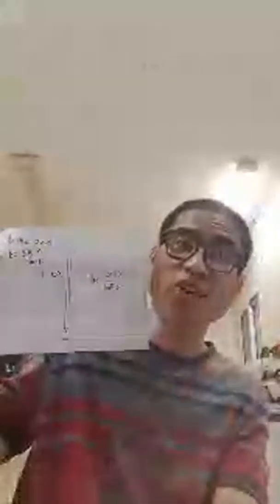Okay, so h is equal to 60 watts per meter squared Kelvin. So what is the denominator, guys? In the convective heat transfer coefficient and convection heat transfer, there's area at the bottom. But for the thermal conductivity, in heat transfer through conduction, only length matters. More on the difference, and bingo, that would be their respective units each. Okay, so you will remember that and put that in your brain cells. Get the point?